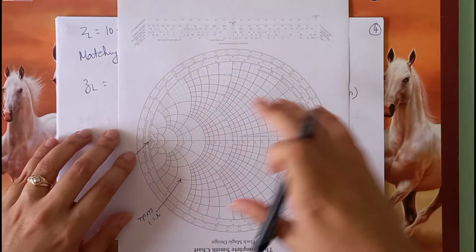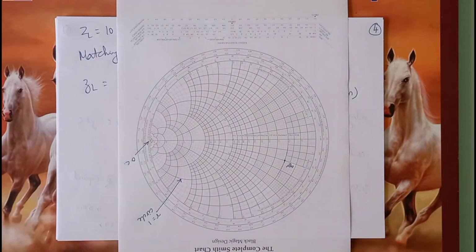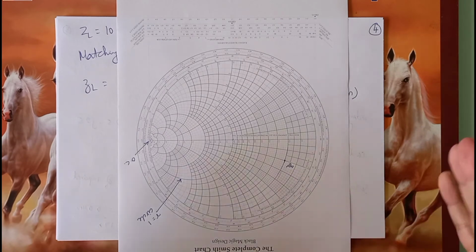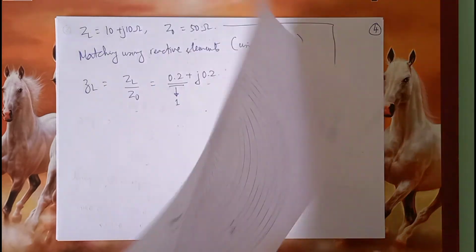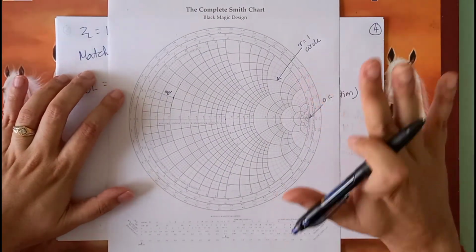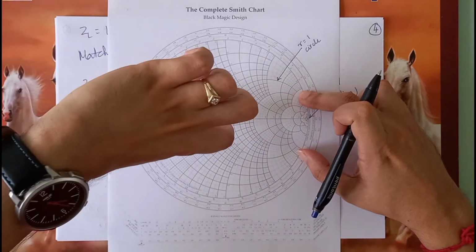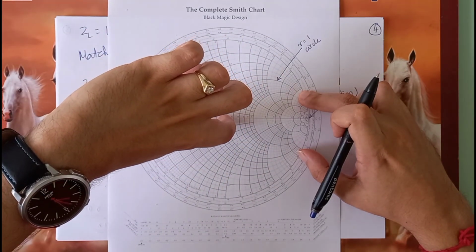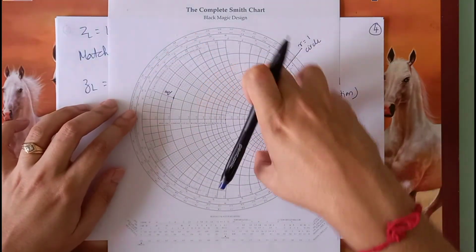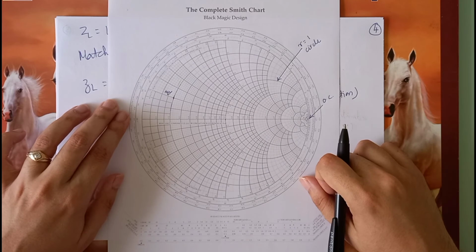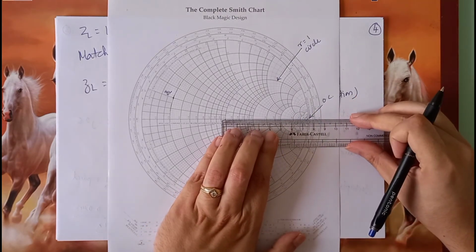So what is happening? Earlier, the R equal to 1 circle was here. Now it has moved here. So this now becomes the G equal to 1 circle. Well, this might sound very confusing because we are not used to rotating the Smith chart so easily, and that is what we don't want to do. So rather than rotating the Smith chart, what we can do is make a copy of the R equal to 1 circle and rotate it such that it comes here. This is the circle inscribed over here, which is a copy of this, and just rotated by 180 degrees would become the G equal to 1 circle. So therefore, let's do this. So let's construct the circle quickly.